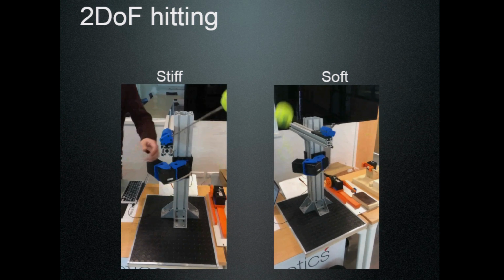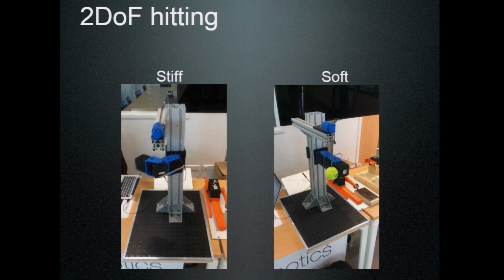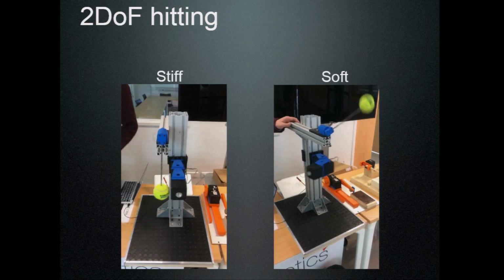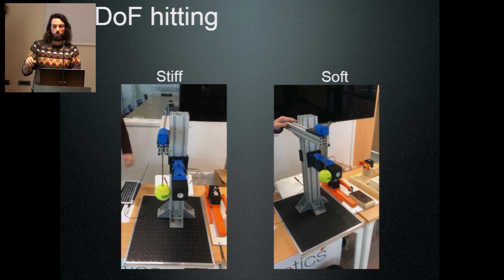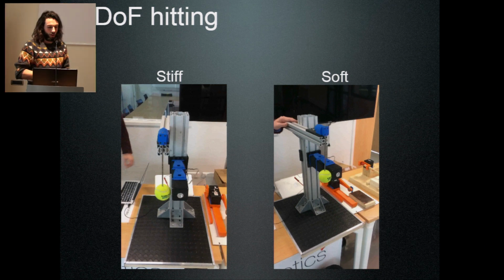Also, we tried with 2 degrees of freedom. You can see the comparison again between stiff and soft configuration of the robot. In this case, it can be proved also in the multiple degree of freedom case that the control is bang-bang-like. We are going to see it. Then for the switching instances, in this case, we have optimized them experimentally by trials. So we optimized them for the stiff case and for the soft case.